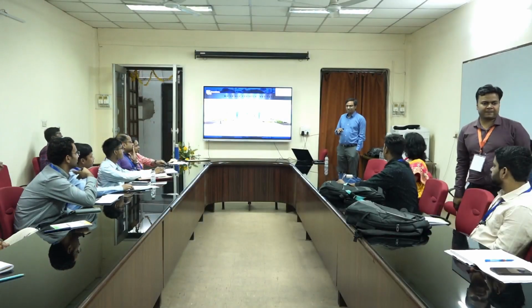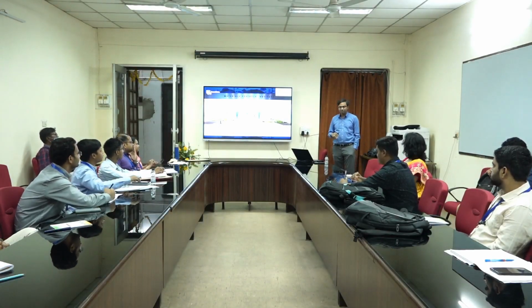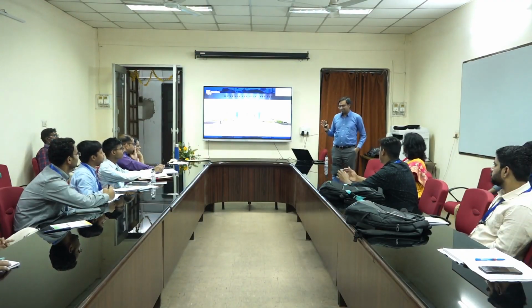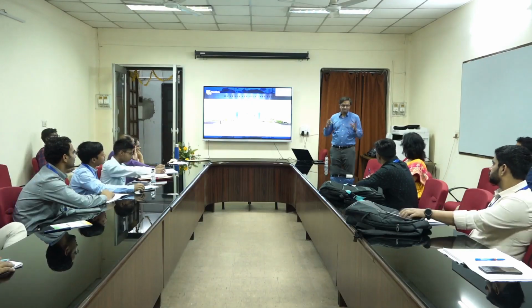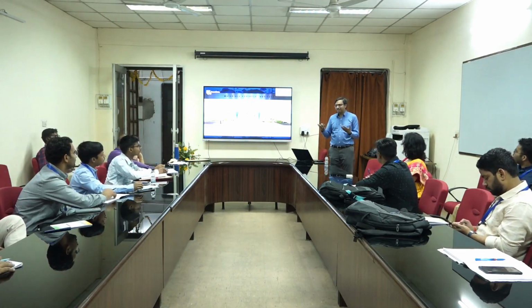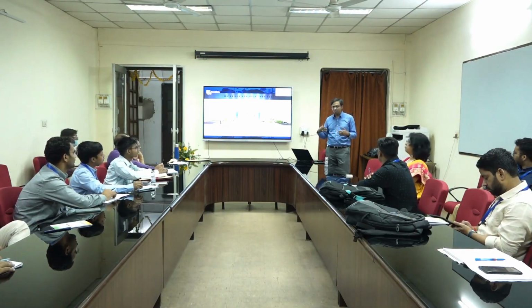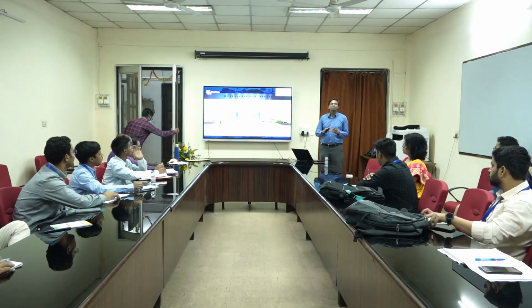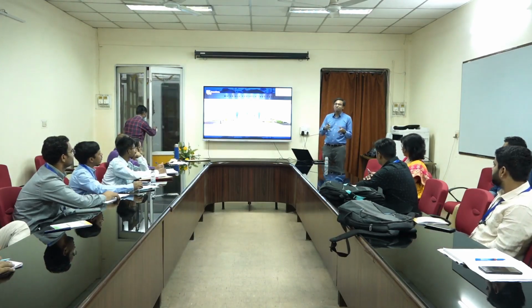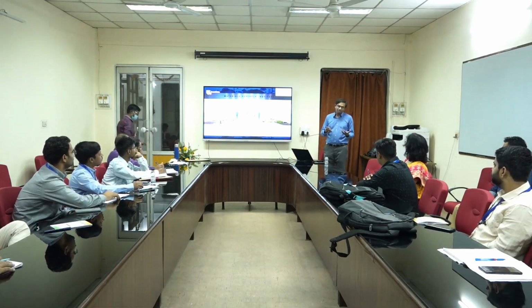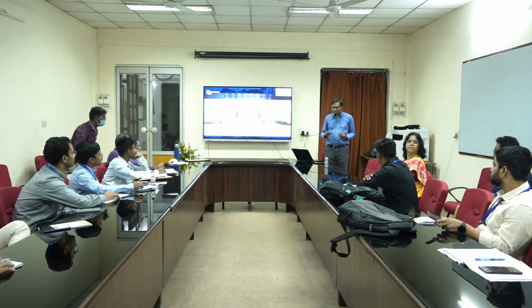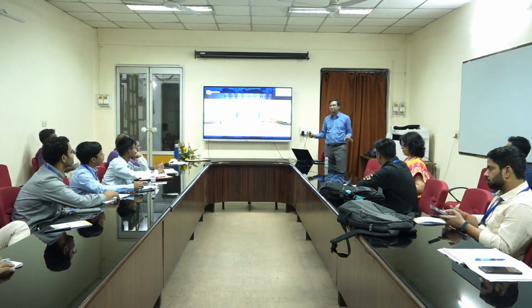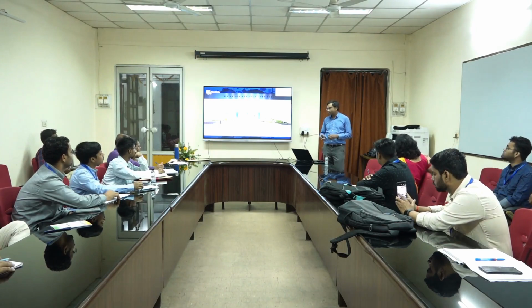We are going to learn a little bit of fundamentals, right, contacts to 2D material, because at the end of the day, when you make any device, you have a material, you have to connect it to the external world, and the connection is really the metals that you put on top of this material. So therefore, contacts to 2D material is one of the key. Unless and until you can make a good contact to the material, you cannot really get high performing devices, and it is true for electronic devices, optoelectronic devices, neuromorphic devices, memory devices, anything that you fabricate.